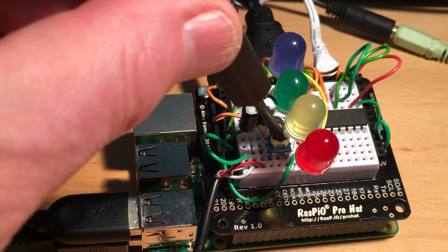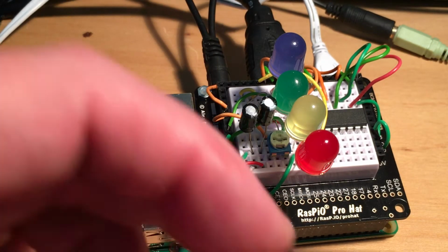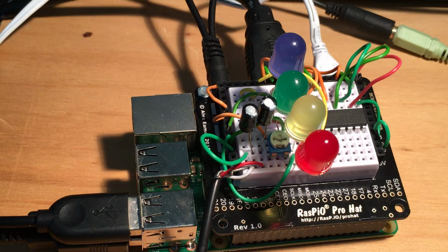So I'm going to adjust the red LED so that it's just out, put the screwdriver down, and we'll now start Sonic Pi running from the keyboard, which is Alt-R, and here we go. And you can see the LEDs responding to the audio input. They're responding to the amplitude. You'll also get effectively a frequency response because as the signal varies, they dim in and out. The blue one is responding to peak signals, the green to slightly less, the yellow to slightly less, and the red to any signal whatsoever being picked up.